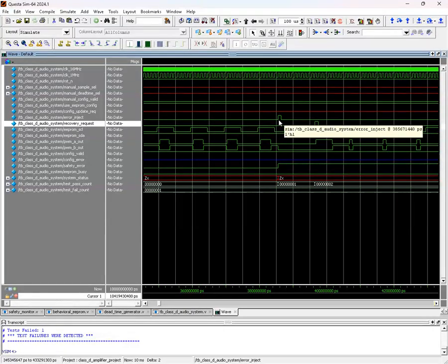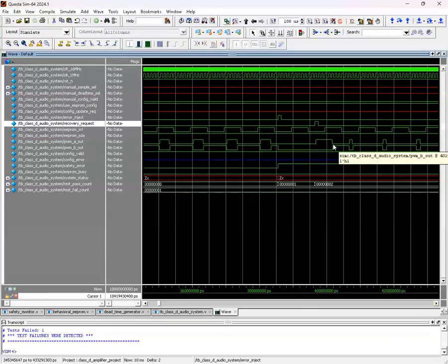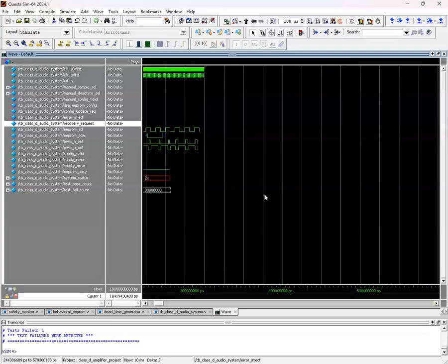If you want to hold the information, if you want to resume from the information, when you recover you could literally recover from the information itself. And instead of coming back with the original PWM from wherever the signal is coming from, you could demand a soft start. So this could start from soft, going up. It's that flexible in that sense.